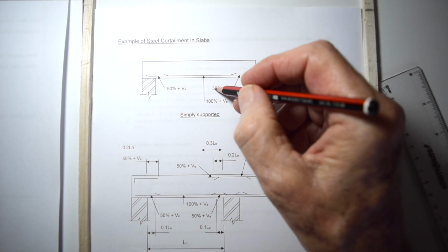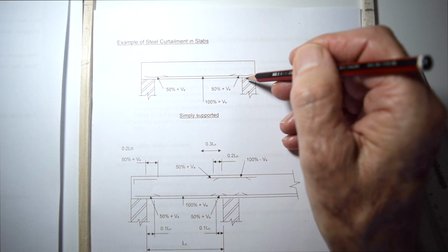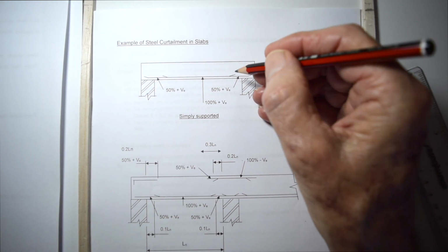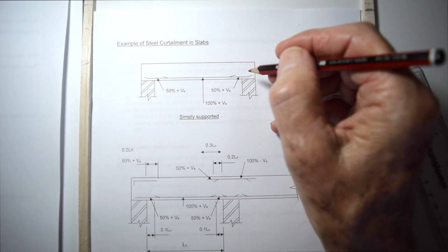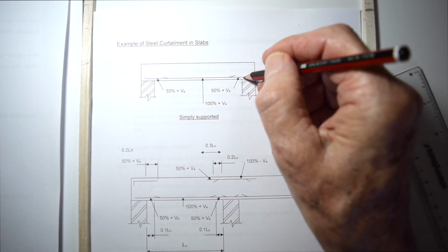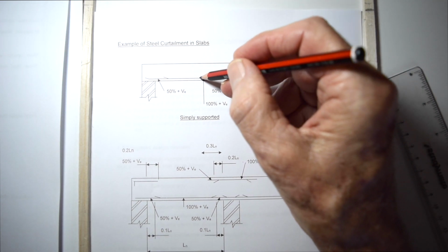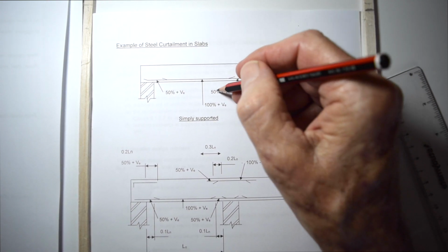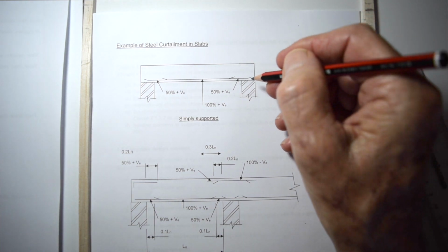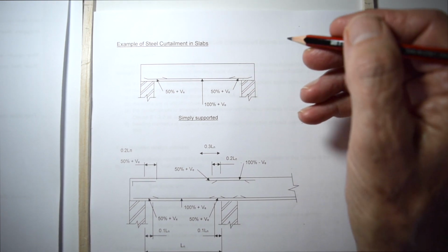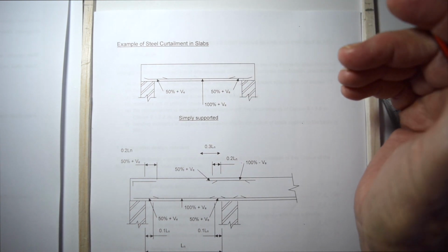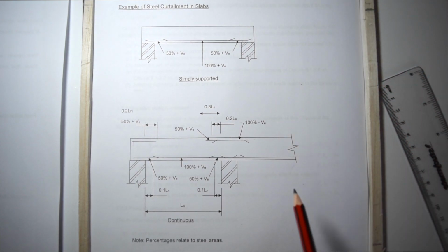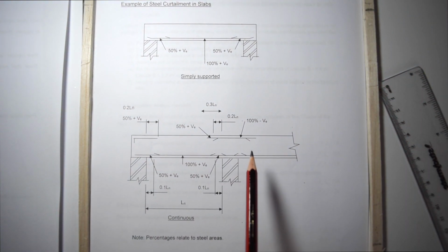So you can then run 50% of this total area through onto the support. In other words, your N12s at 250 will go through to there, and over there your N12s at 500 will go through to there, because in this section here you've got N12s at 250. That's already selected. If we run every second bar through to the support, which gives us 50%, we'll have N12s at 500 running onto the supports. Bear that in mind. You can do that in economy. I haven't done it in any of the examples, but the code says you can do it, and they're quite right, you can.